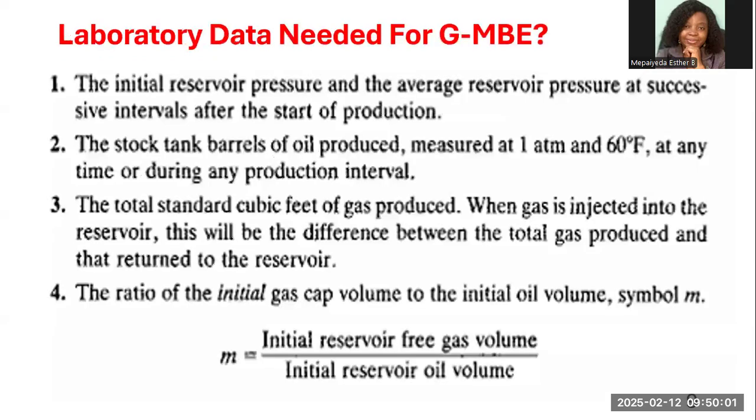Okay, let me also mention that other PVT data are also needed, your Rs, your solution gas oil ratio, needs to be measured. So you have different experiments that can be carried out in the laboratory on samples of oil taken from the reservoir.